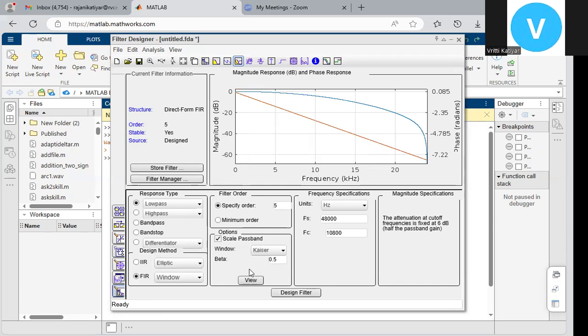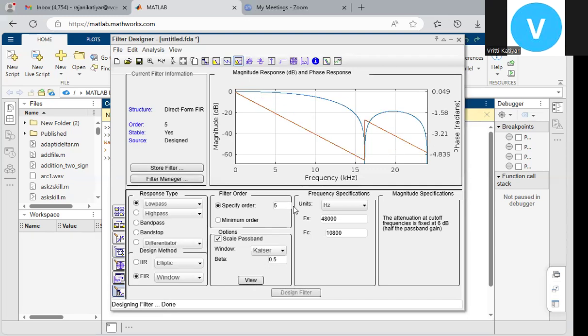We'll analyze the behavior of the Kaiser window for the design of the FIR filter, and we'll see in which way this is different from the previous two windows. Again, we can see the linearity and then the side lobes. The side lobes are still more, so we can see how they can be minimized further with the other parameters we are considering. We can change the parameters, analyze, and fix at which particular frequency we are looking for the linearity property of FIR.